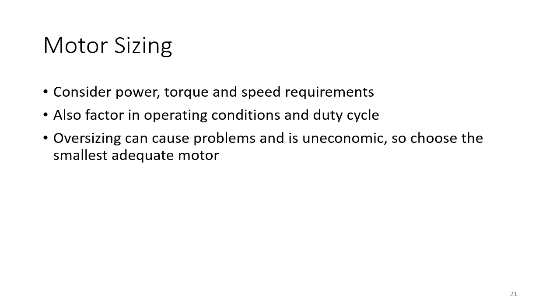Now it's important to size the motor and the VFD correctly. For motor sizing, typically what you'd be looking at is the amount of power and torque and speed that's required for the application. That would normally come from a consideration of the mechanics, what sort of devices you're powering. If it's a conveyor, you'd need to consider how heavy the conveyor belt is. You'd need to consider how much load is going onto the conveyor, and that would give you your power and torque requirements. Along with the gearbox, you'd need to know what the speed requirements are so you can make sure that the conveyor can operate at its required speed.